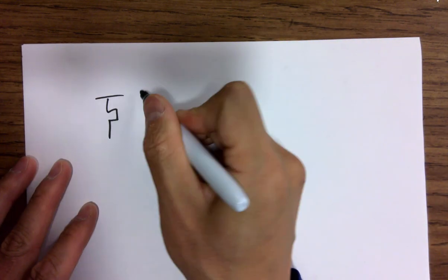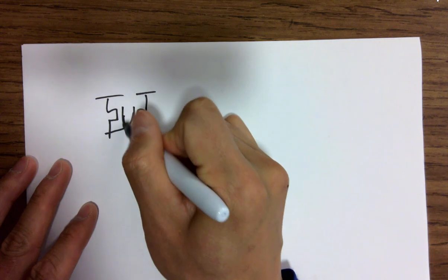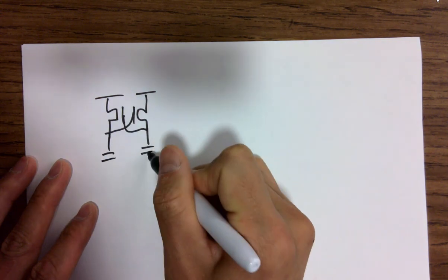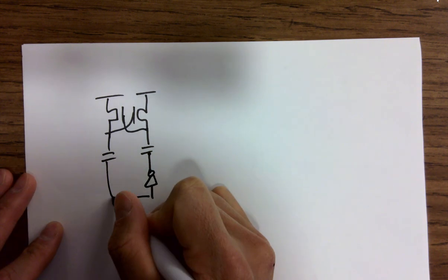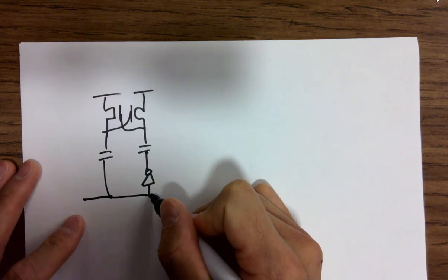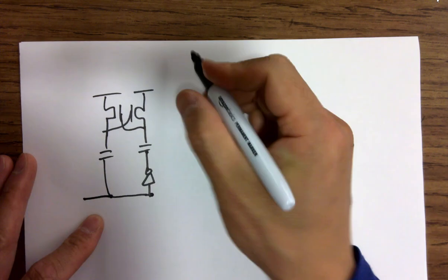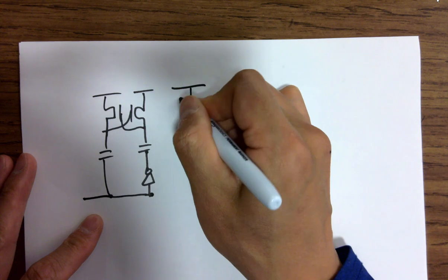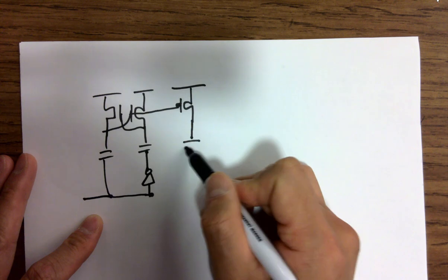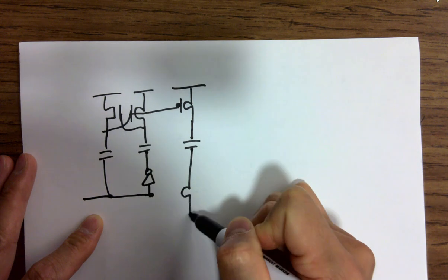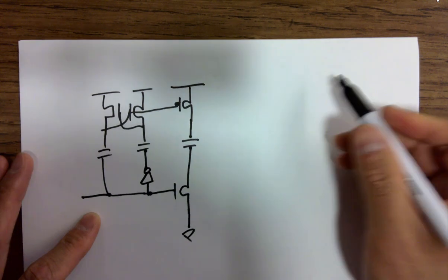So that's the circuit you want to use for the sample and hold, right? So the sample and hold circuit looks like this. You need these basic components here. You do this, cross it, charge pumps. And here's a signal line. You have another NMOS here, and that takes this voltage, and you got a capacitor, and this one shorted to ground.